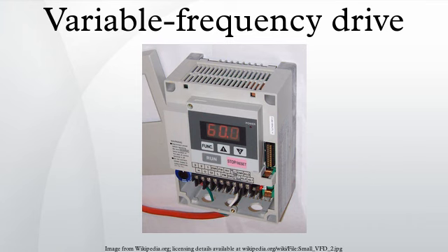In large motors, the stray capacitance of the windings provides paths for high-frequency currents that pass through the motor shaft ends, leading to a circulating type of bearing current. Poor grounding of motor stators can lead to shaft ground bearing currents. Small motors with poorly grounded driven equipment are susceptible to high-frequency bearing currents. Prevention of high-frequency bearing current damage uses three approaches: good cabling and grounding practices, interruption of bearing currents, and filtering or damping of common mode currents.